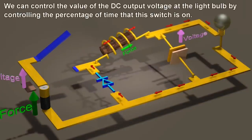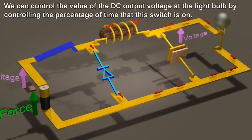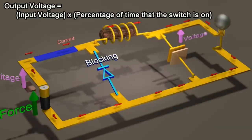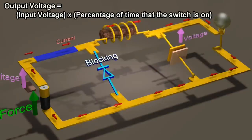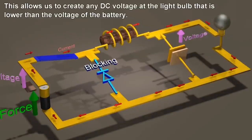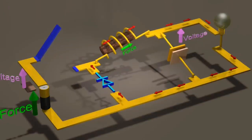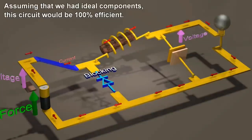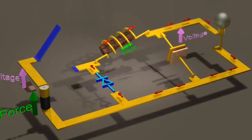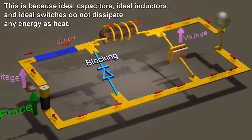We can control the value of the DC output voltage at the light bulb by controlling the percentage of time that this switch is on. This allows us to create any DC voltage at the light bulb that is lower than the voltage of the battery. Assuming that we had ideal components, this circuit would be 100% efficient. This is because ideal capacitors, ideal inductors, and ideal switches do not dissipate any energy as heat.